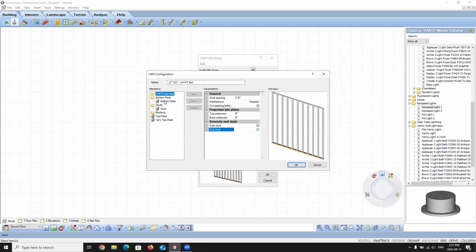Now the bottom plate, like I mentioned, we are now using, instead of the stud option where we're saying wall properties, again, if we're drawing with 2x4 walls or 2x6 walls, it's going to use the appropriate stud. We're saying that when I draw a 2x4 wall, I need it to use a 2x4 pressure treated bottom plate. So that's why it's using that there. This is all done so that you are getting the correct quantities in your reports when you draw out your designs. So this way you're going to see exactly how much 2x4 treated material you're going to need as a sill plate in your designs.